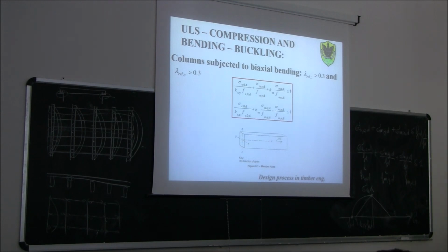Note that for reinforced concrete we were drawing a global M-N domain, bending moment and axial force. For timber, our domain is in terms of stresses. Okay, so sigma n versus sigma t, or in this case sigma c, compression. So we need to make sure that our strength demand, for example sigma c0d, is inside this domain.